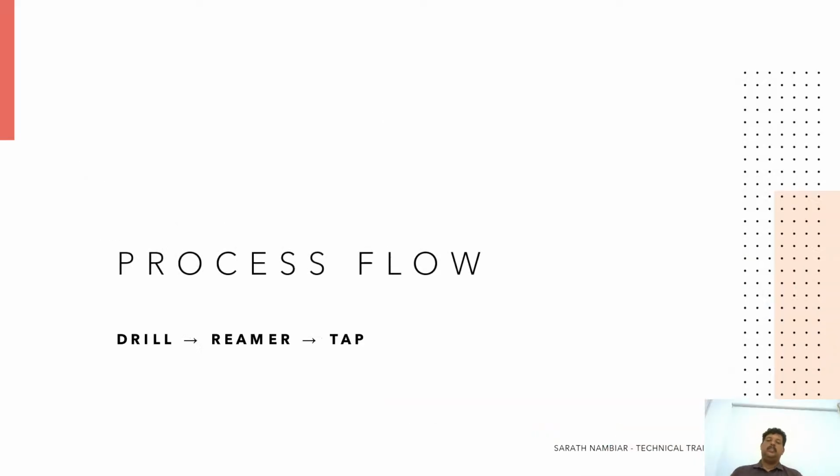Now, process flow. How does it work? How will we do it? First, we will drill. Then we will use a reamer if necessary, and then we will use the tap. This is the proper procedure.